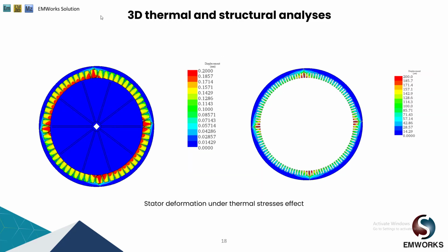It is also very important to analyze the stator deformation under the thermal stress effect. For the overall stator, the displacement was around 0.2 mm, but looking at the deformation of a particular stator core, the total displacement was around 200 micrometers.